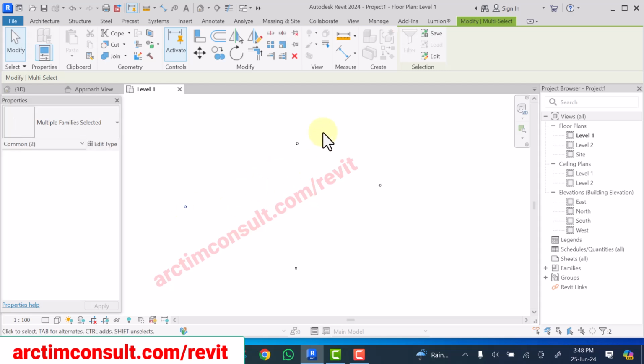So you can move them backward so that whatever you are doing should be in between the markers, because these are what gives you your elevations. All right, if that is done, the next thing I will do is I'm going to create my levels.